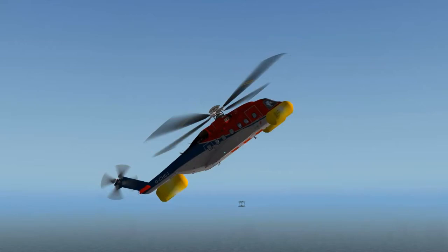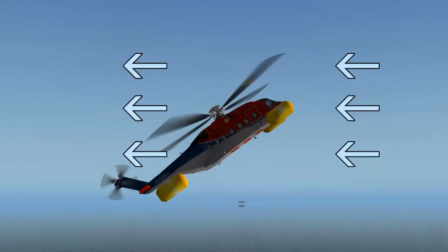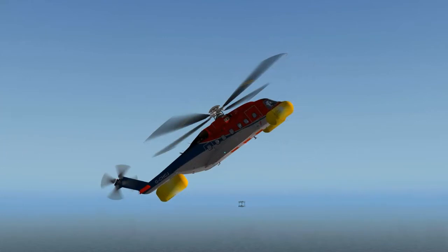Now, as you slow down, the force of the relative wind moving through the rotor system unfortunately slows down as well. So this is it. That is all that was keeping your rotor spinning, and now it's gone, or it's below a point at which it's useful. It can't keep the blades spinning as fast as you need them to anymore.